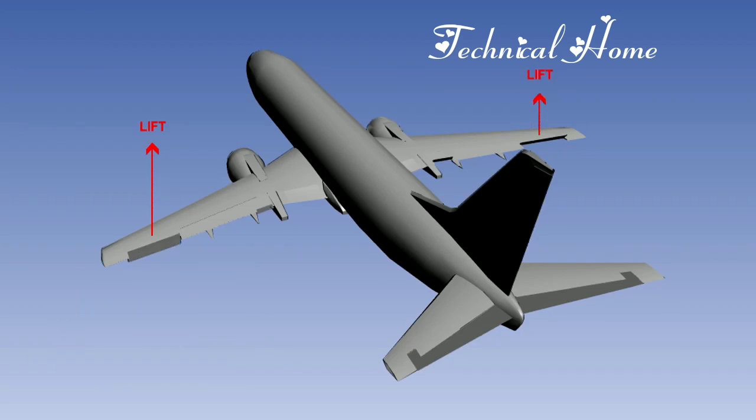The ailerons are flap-type controls, but their angular movements are in opposition to each other. When one aileron is angled up, the other is angled down. Consider the aircraft in the graphic. The left wing has the downgoing aileron. This will increase the camber and increase lift. The upgoing aileron on the right wing has a reduced camber, so its lift will be reduced.